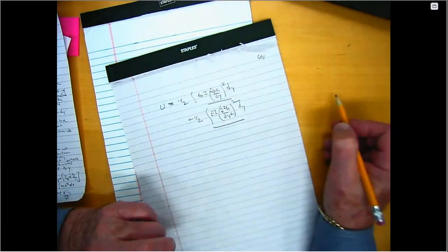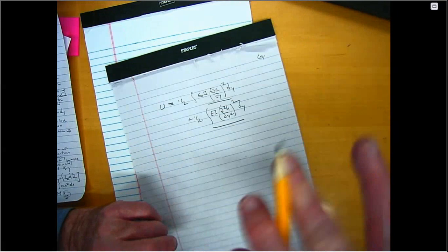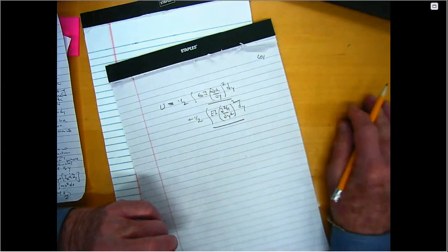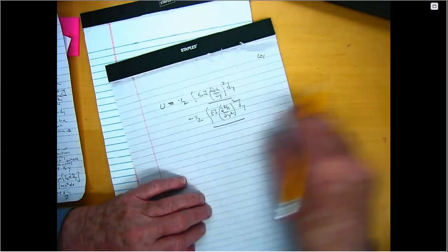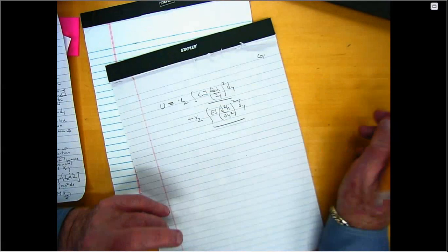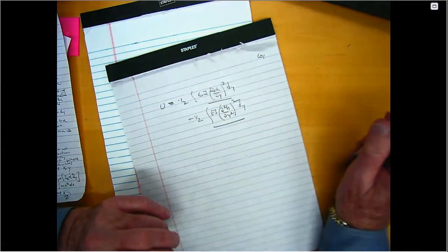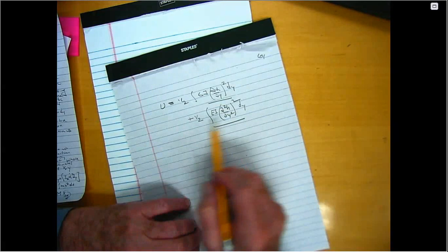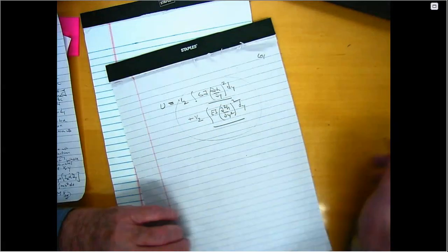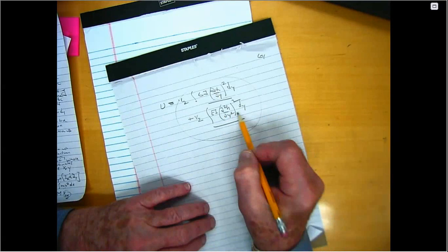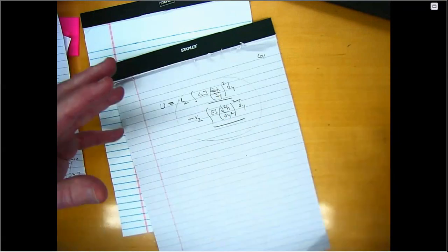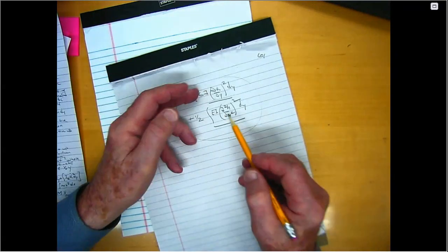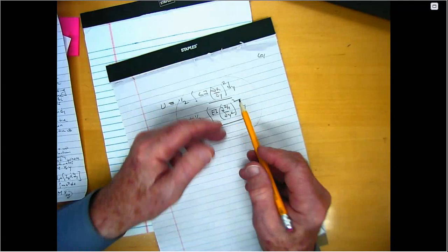So I'm treating this wing as having pure twisting about the elastic axis and pure bending of the elastic axis. And one reason we choose the elastic axis is because if I do that, then in this expression for U, there's no coupling between alpha and h, right? The terms appear separately. There's no cross term, right? There's no derivative of h times some derivatives of alpha.